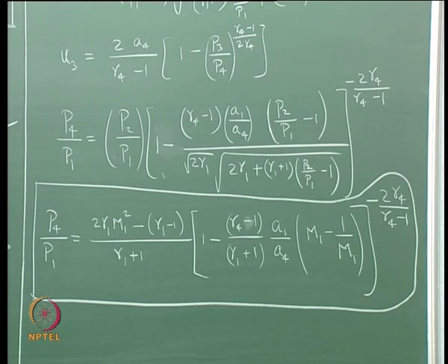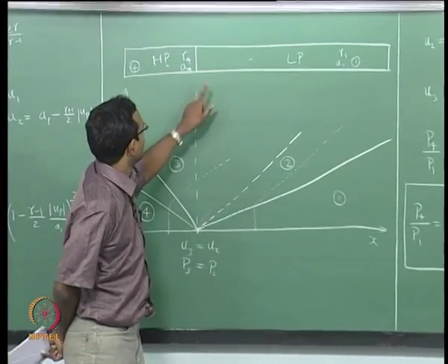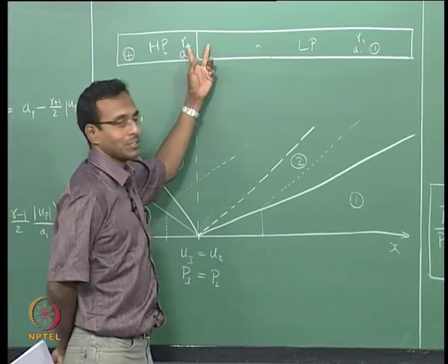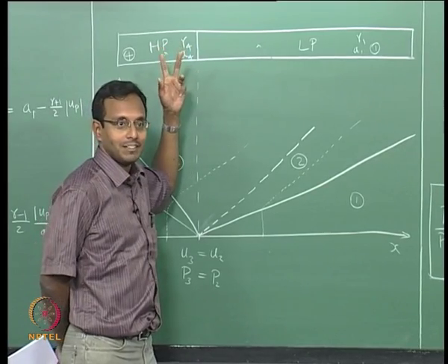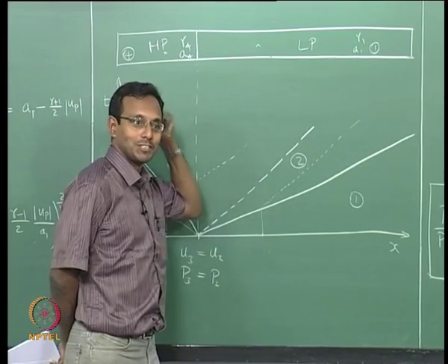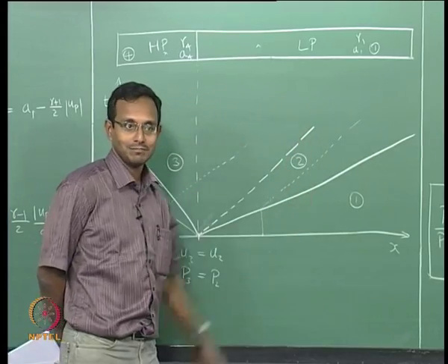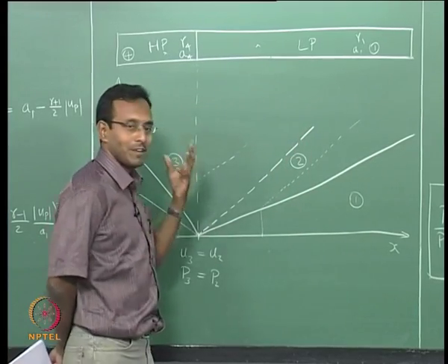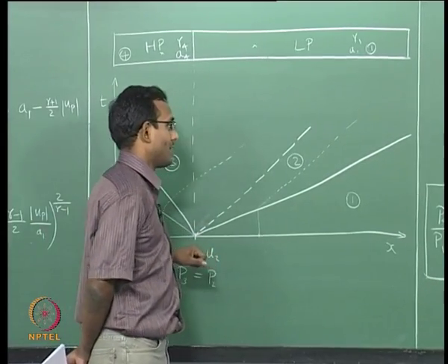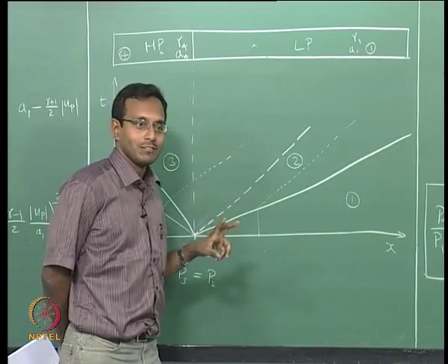If I think about wanting a very high Mach number, what should I do? From physical feel, I will look at this picture, it is easier to think about. I want the shock here to travel very fast. What should I do? The jump in pressure should be really high, right? Then the information that is traveling will say, run extremely fast, because there is so much crowd there and nobody here, just run extremely fast. So, just by physical intuition we will keep that, it will help us a lot. So I want to maximize my M1, what should I do?